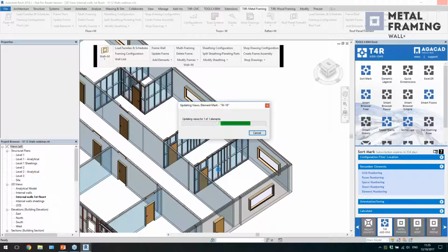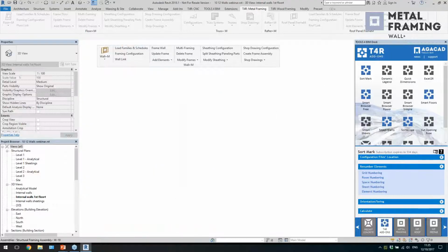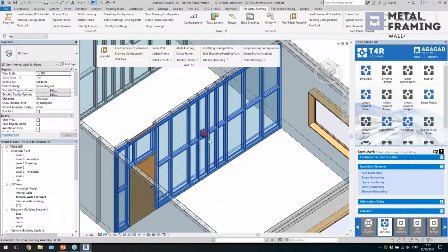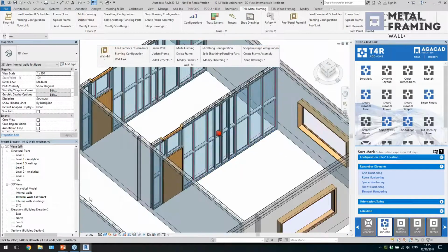So it will gather all the details and framing elements into one assembly. Then it will create views, apply view templates, place dimensions, and place these views on the sheet. It will read information in the template project on how the views should be placed. And you see now I have this red dot, so this is the gravity point.